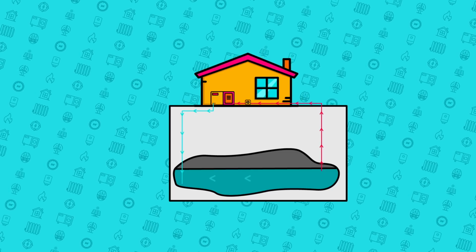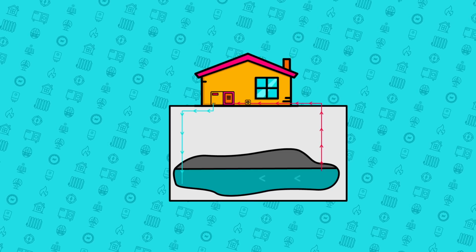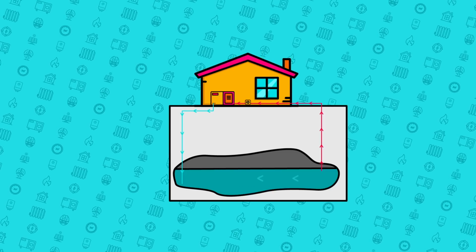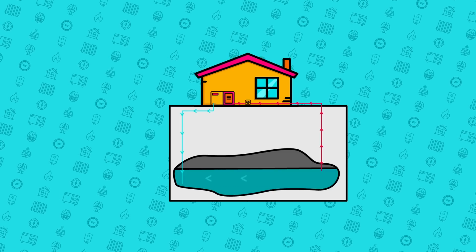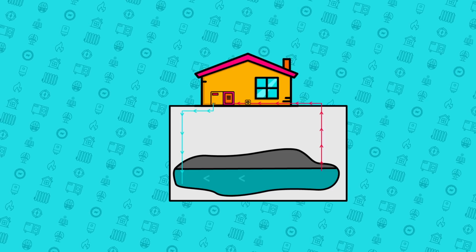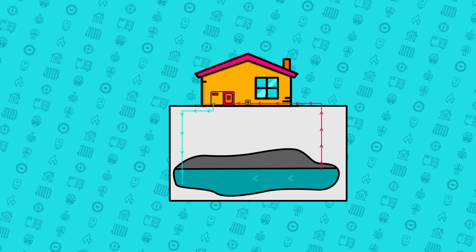The advantage of open loop is that there is slightly better heat transfer into the heat pump system. However, the pump needs more power to draw the water up, and it can be difficult to get right, so it needs experience and a specialist, and does need more maintenance, as there's a filter to clean on a regular basis.